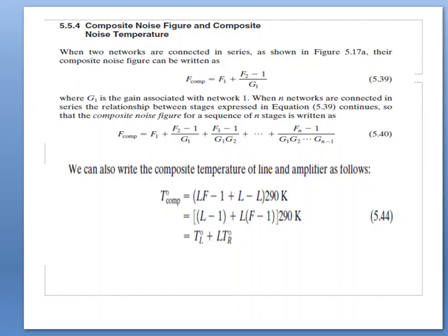Can you guess from the above equation what the design goals for the front end of the receiver should be? At the front end of the receiver, the signal is susceptible to added noise. Therefore, the first stage should have as low a noise figure F1 as possible, and also because the noise figure of each subsequent stage is reduced by the gain of previous stages, we strive for as high a gain G1 as possible. Simultaneously achieving a low F1 and the highest G1 represents conflicting goals.